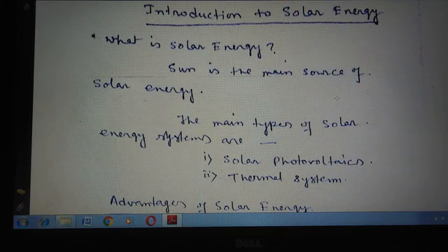Now, the solar drying system is also an application of solar heating in a solar thermal system. Drying has been the oldest and most widely used application of solar energy in developing countries. The methods are very simple. In a solar dryer, the ambient air is heated and passed into the drying chamber by natural convection. The hot air removes moisture from the crops and becomes cooler and falls to the bottom of the drying chamber. By this system, different types of products are dried.